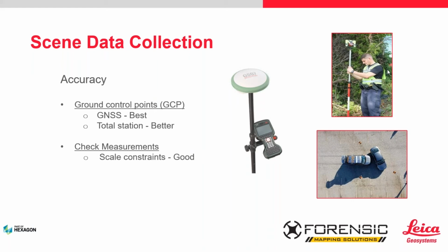So first, a ground control point, I had said it's a known point, an anchor, but in the photogrammetry software, you need to have targeting or some type of marking in the area. If you look at the bottom right of that slide, it's a little hard to see, but you can see there's 3 targets there that we would then use either our total station or GNSS GPS to capture the location of those points.